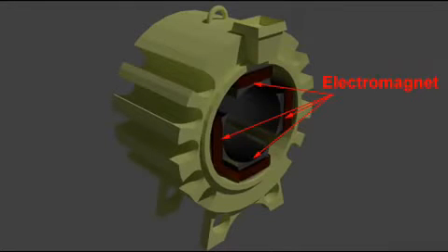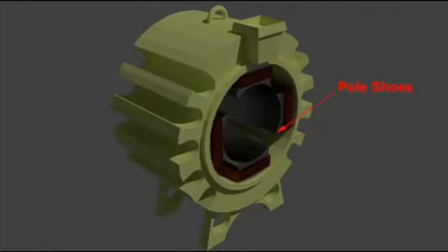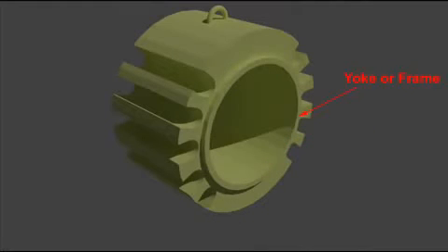The field magnet system consists of four main parts: yoke or frame, pole cores, pole shoes, and magnetizing coils. The yoke is generally of cylindrical shape. The yoke acts as a cover frame of the machine and carries the magnetic flux produced by the poles. Since the field is stationary, there is no need to use a laminated yoke for a normal machine. In small machines, cast iron yokes are used because of cheapness, but the yoke of a large machine is made of fabricated steel due to its high permeability.